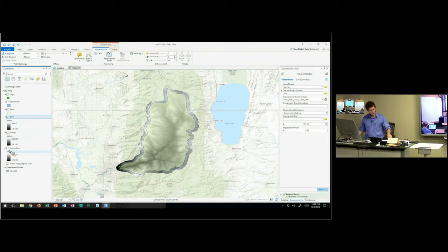So you can look at the properties. A comment here: you chose the UTM coordinate system. Maybe you wonder, well, why UTM coordinate system? One of the reasons is that that's the coordinate system used for search and rescue. So if there's any rescues that have to be done in this area, they say helicopter go there, airplane go there. Always the coordinates are given in UTM coordinates. So there's sort of an operational reason for emergency response for using this coordinate system.